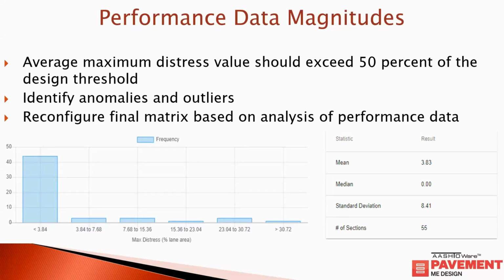It's the legwork doing the test section selection, going out there, collecting data, scrubbing the data to match the pavement ME design outputs, doing a lot of materials testing, all that stuff up front. Once you do it initially, you're not going to have to do that again. Mostly what you're doing is just adding more performance data and including that in future calibrations.